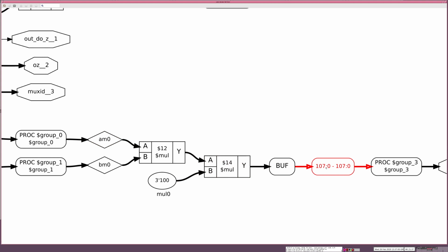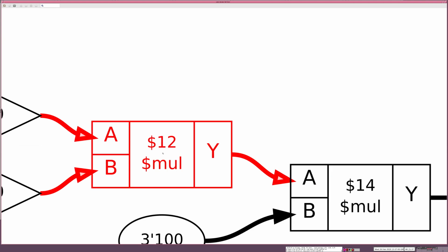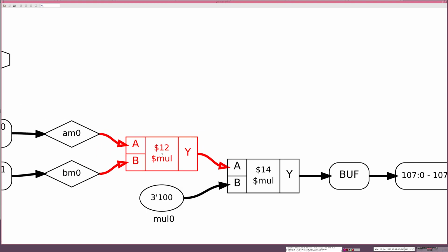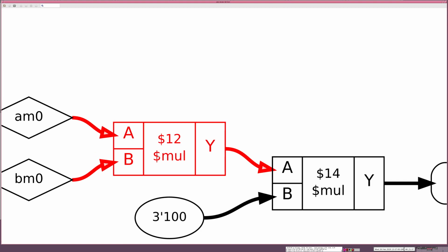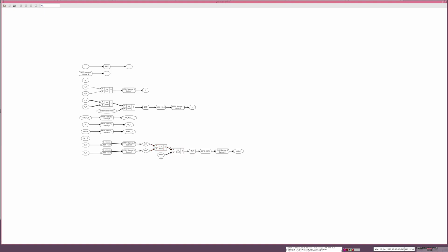That's completely not possible. So this block here is going to have to be replaced by a multi-stage pipeline involving a data multiplier. We would use the integer partitioned pipeline and just say, please do this: a 64-bit in, 128-bit output, but we'll just use 107 bits of it only. So there's another set of stages in here, but this is massive. If we left this single block on its own for yosys to create, it would be absolutely massive. So don't be fooled by that one single looking block.